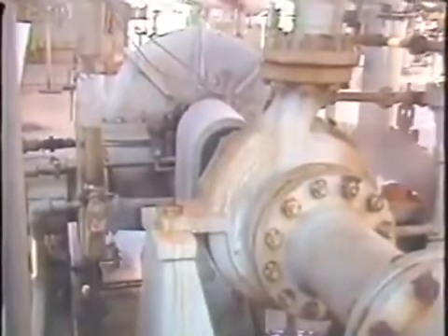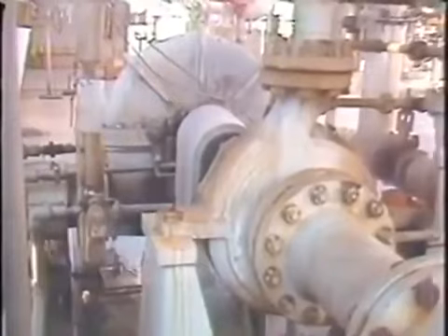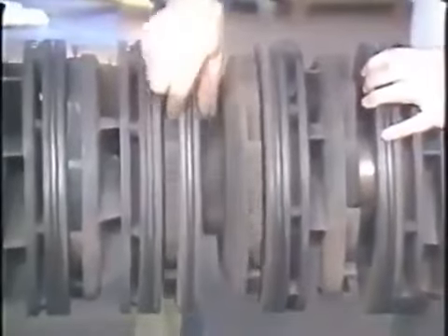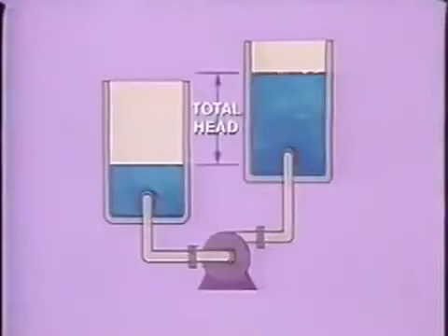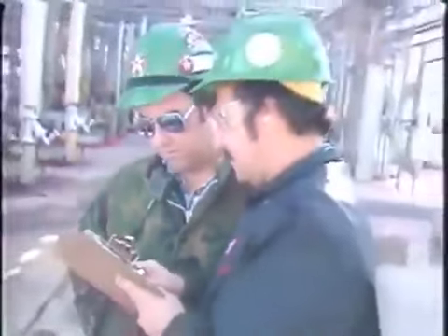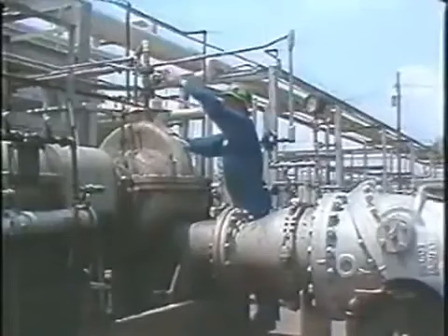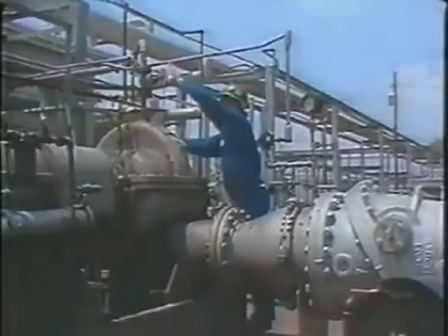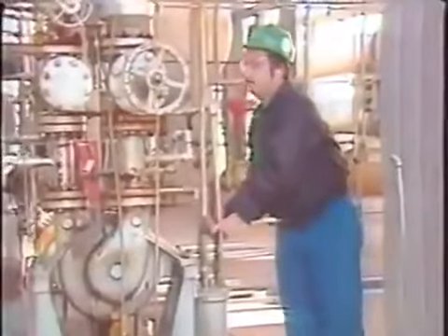In this program, you've learned how pumps add the energy necessary to move a liquid from one location to another. You also learned how certain pumps make use of centrifugal force to add velocity to a liquid in order to move it, and how various types of impellers and casings may be used in the design of centrifugal pumps. You learned the meaning of the term head as it is used in reference to pumping liquids, and how pump performance curves may be used to help set a pump to perform at its best, given other operating variables. Finally, you learn various methods of priming a centrifugal pump and why this is important, and some typical startup and shutdown procedures.